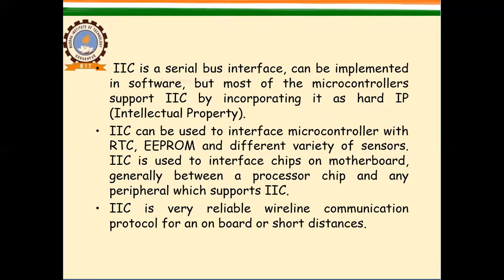Then we discussed the general principle involved in I2C. It is also a serial bus interface. And the most useful thing is that if we have several microcontrollers connected in an embedded system, or in any project where you are going to use several microcontrollers, then SPI is not a feasible solution for transmission because it only supports a single master.